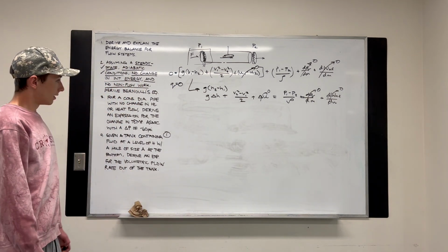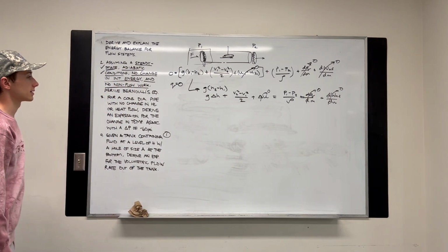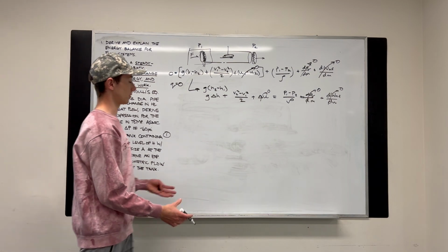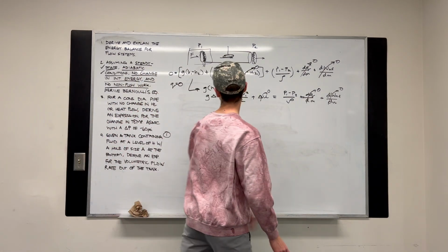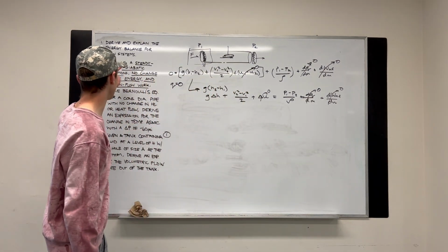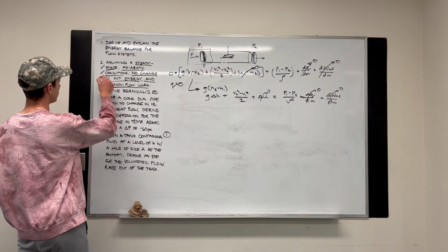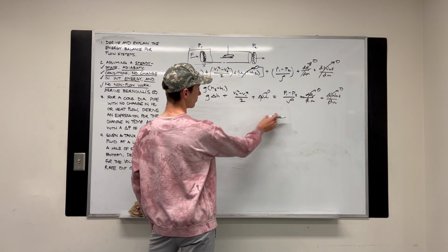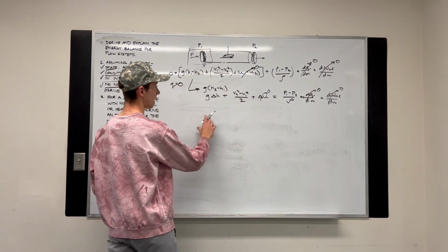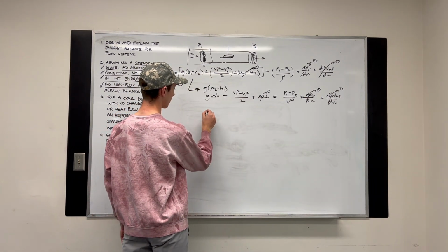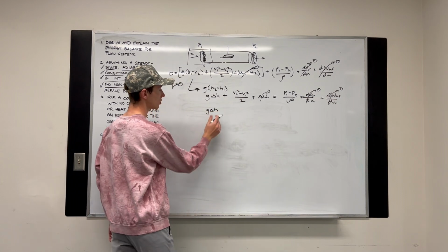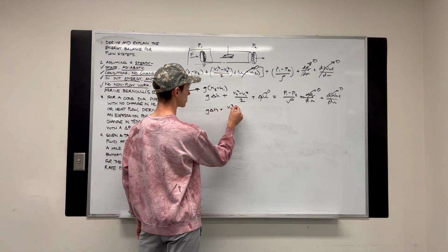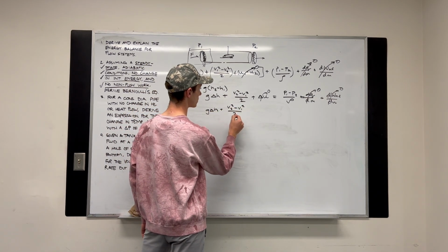Really this is the relationship that is Bernoulli's equation as it's most thought of, when we have steady state, adiabatic conditions, no change in internal energy, and no non-flow related work. We can make it look a little bit prettier if we put our work on one side and set the whole thing equal to 0. So now we have g delta H plus V2 squared minus V1 squared over 2.